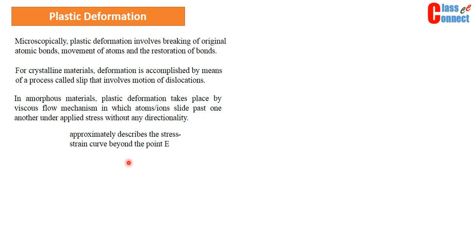We can relate stress and strain in plastic deformation, that is basically the portion of the stress strain diagram between Y to U. Though the plastic deformation starts beyond E, the point E, that is elastic limit, and Y are practically very close to each other, and we use this Y yield point strength in general for all design purposes. So that is why we consider that these both points are coinciding.